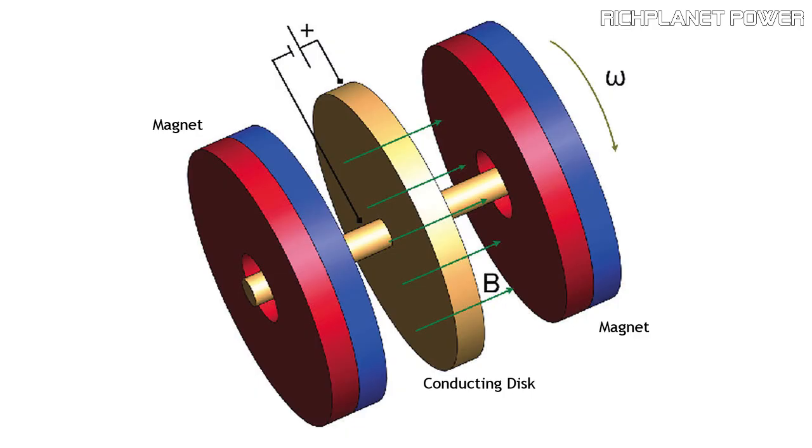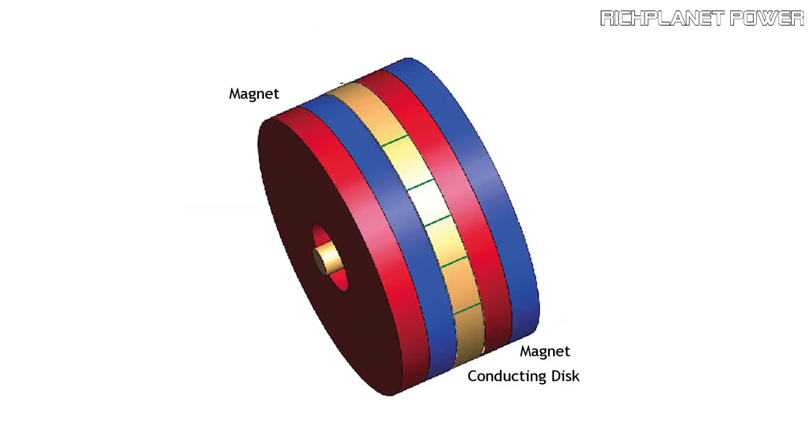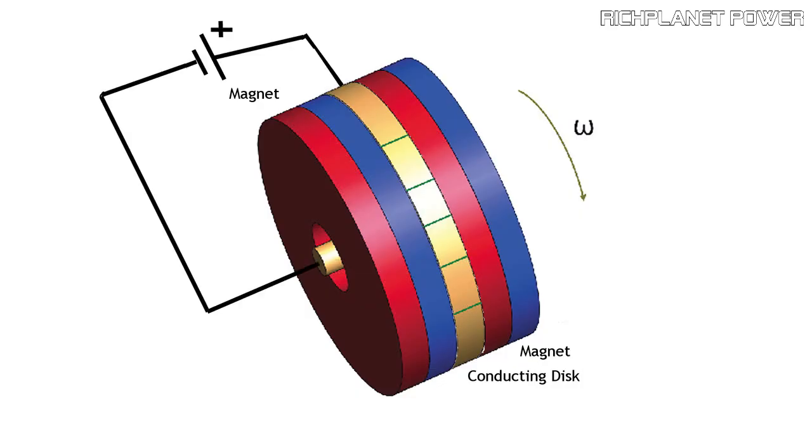The magnetic field can be produced using two circular magnets positioned either side of the disc. Usually the magnets remain stationary while the disc spins in close proximity. However, Michael Faraday discovered that if the circular magnets are attached to the conducting disc and then rotated with the disc, known as co-rotation, a voltage and current are still produced. This puzzled Michael Faraday because there is no relative motion between the magnets and the disc, and he was so surprised that this became known as Faraday's paradox.